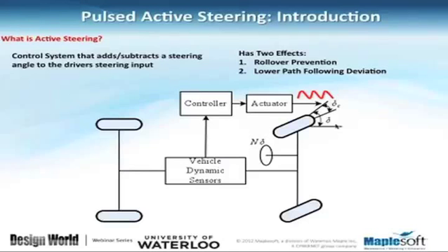It becomes less sensitive to the road conditions, and in terms of implementation, it is much easier. So if you look at this diagram as the overall picture of a vehicle, then on the front side we have the steering angle. Let's call that delta, which is the input from the driver. And then we have a controller that is looking at the vehicle dynamics, or the yaw of the vehicle, and the yaw that the vehicle should have at that time.